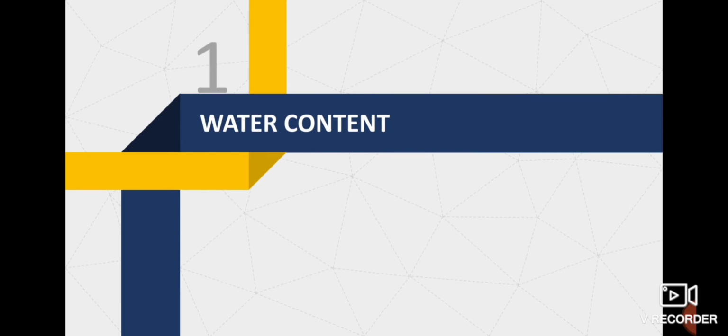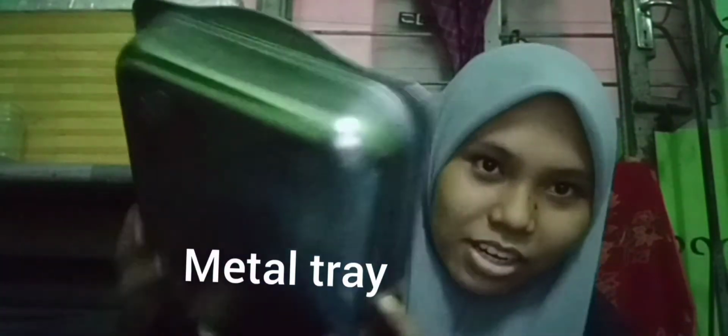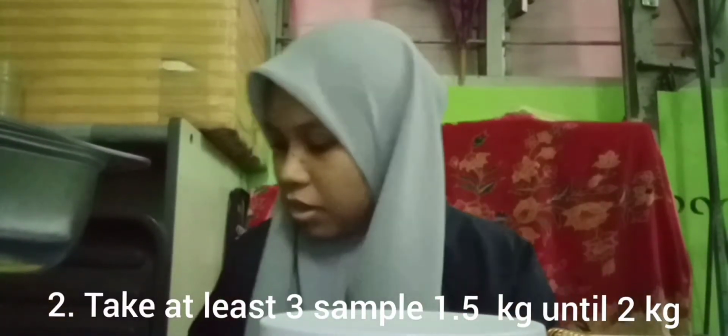First, water content. I will show you the methodology of water content. For the water content, this is the apparatus. First, weighing balance. Second, metal tray. And soil sample. Clean and dry a metal tray and weigh it as M1. I use 3 trays, so you have to weigh them all. Take at least 3 samples. I have 1.75 kg, 1.9 kg and 1.5 kg.